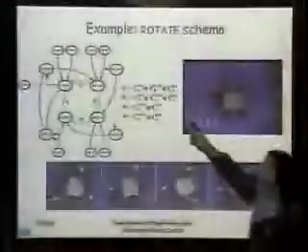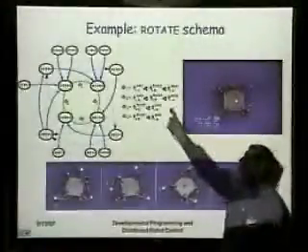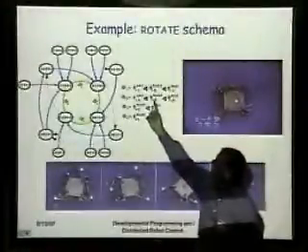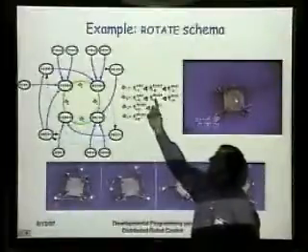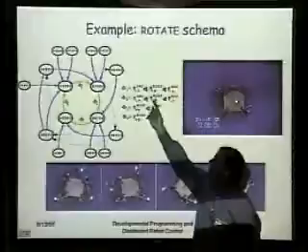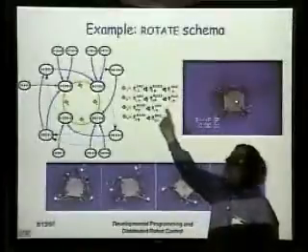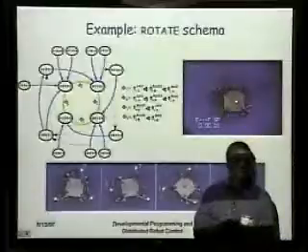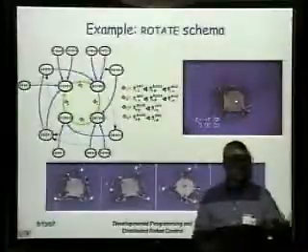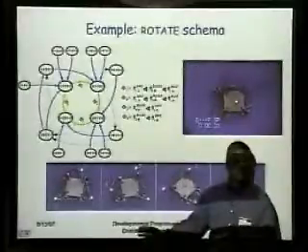These are the actions. These triangles denote null space projection. So this is a primary controller, that's a secondary controller, that's a tertiary controller. This one must project its inputs into the null space of this one. This one must project its inputs into the null space of this one. So the primary controllers are guaranteed to be protected from destructive inputs from the subordinate controllers.